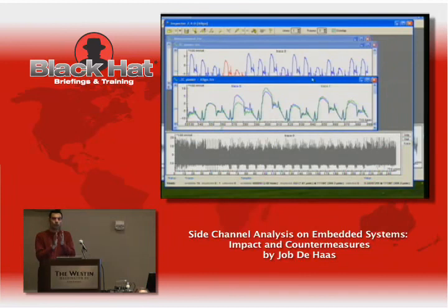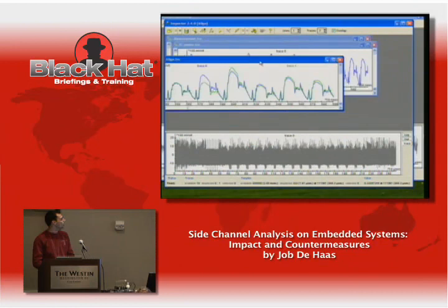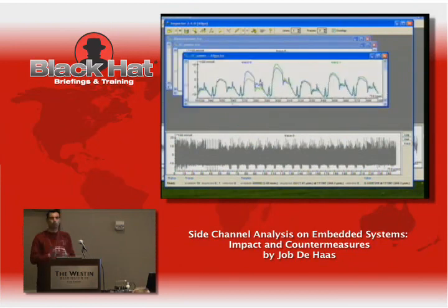Now this is on a clock cycle, but the clock cycles could still be quite out of sync with the process that's actually happening on the clock cycle. So what I showed you in the measurement is that I'm doing an align, then a resample, and then an align again. That's to make sure that the process patterns are aligned and not only the clock cycle. The resampling has to do with what is the interesting information within the clock cycle.